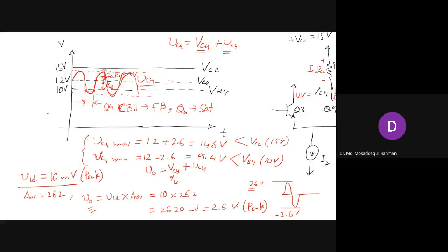So with the circuit that we have, with the different parameters and values as said, the RC1, RC2, the I1, I2, we have the margin here. We have this margin of how much? 2 volt, right? And here we have 3 volt. So this margin actually determines the maximum window we have for the signal to swing.